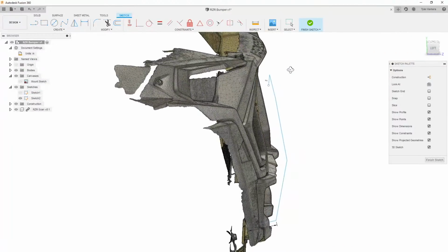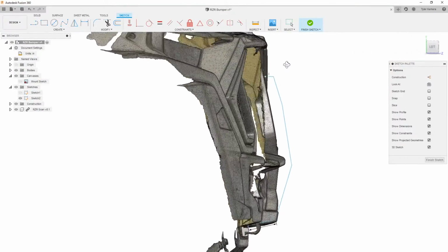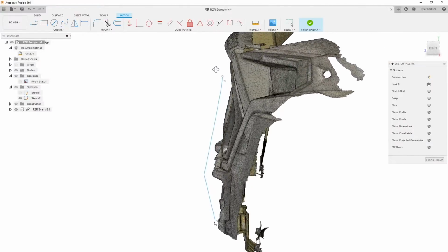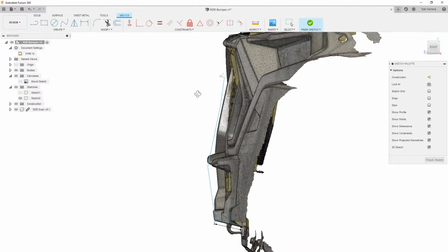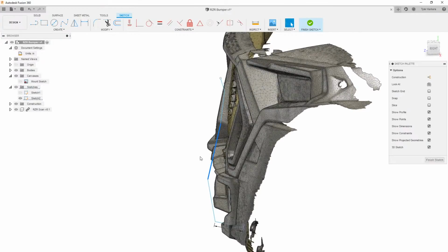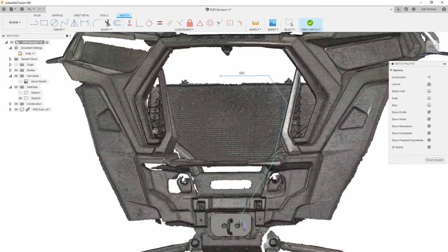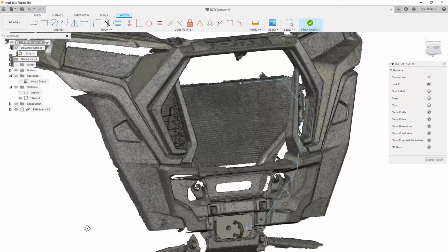And yeah, actually, I like that a lot. That looks pretty good. And of course, there's going to be some material here. It's not going to be just this line that I have to worry about making contact with. It's going to be, I'm thinking, probably a 3/4 inch or an inch diameter tube. So we'll check that in a second and make sure that that's making clearance.